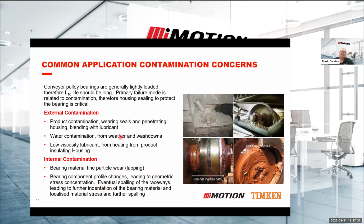So the problem with conveyors is they also get highly contaminated, and one of the issues that we come across all the time is trying to keep the contamination from getting into the housed unit. It's really a very dirty application. It's very fine powder as well, so it causes all sorts of problems with the sealing arrangement. It penetrates through that sealing arrangement quite easily.